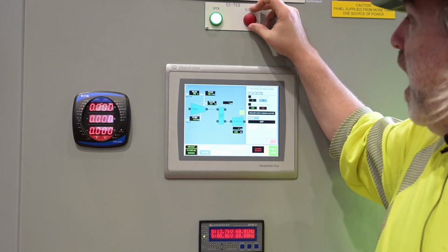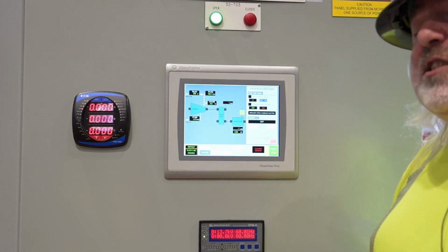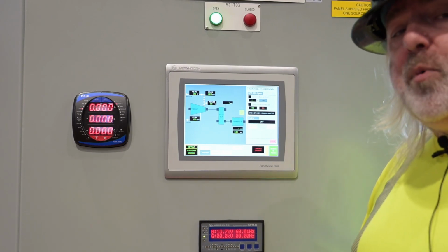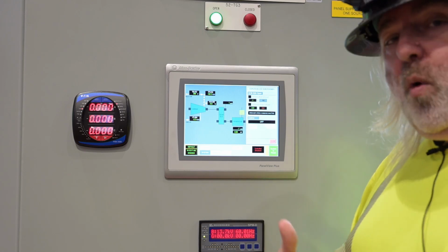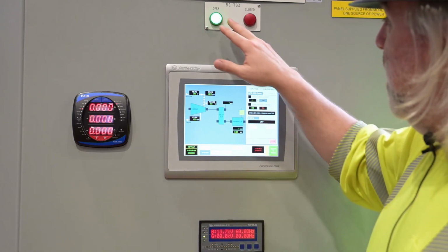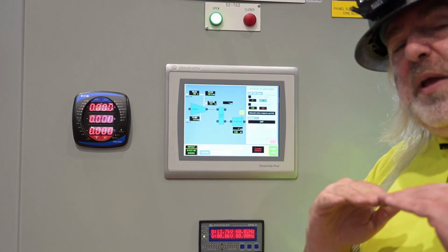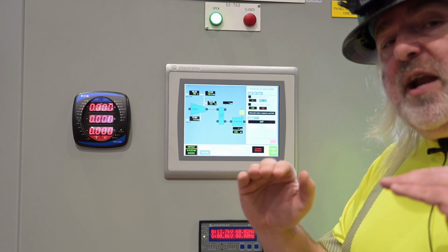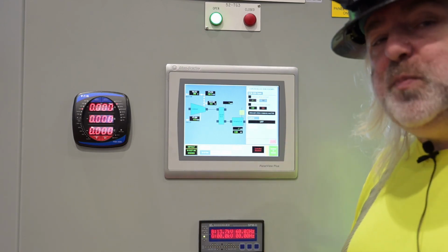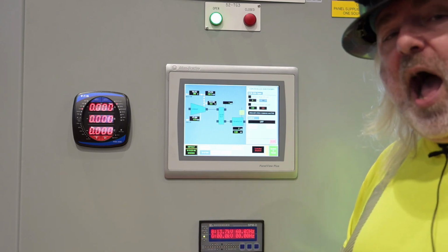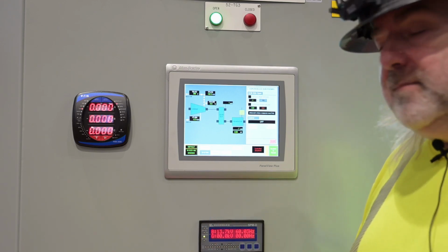If you cancel it while the breaker is closed, the system will immediately go back into normal operation and try and maintain either pressure or kW based on what you've got for a set point. If the breaker is open, the speed set point will stop at whatever it is and stay there until you as an operator change that speed set point, either by going to idle or rated, or putting a different number in.